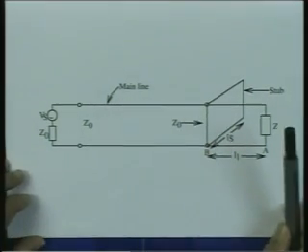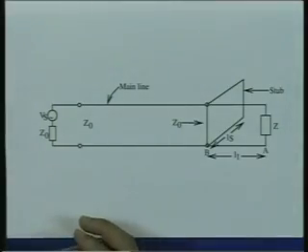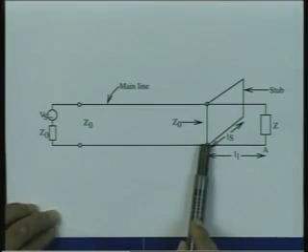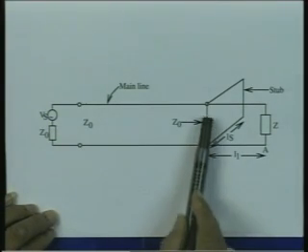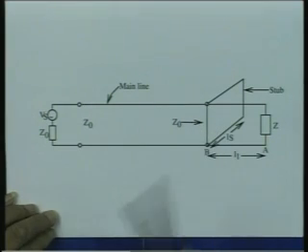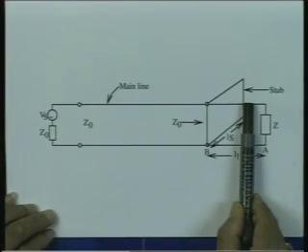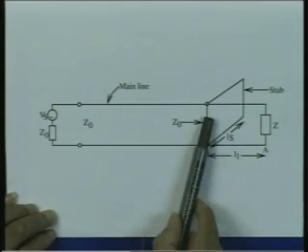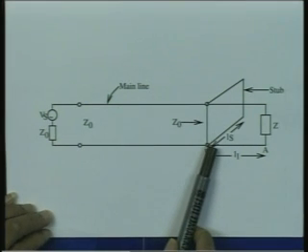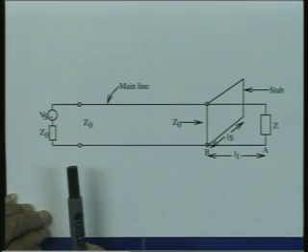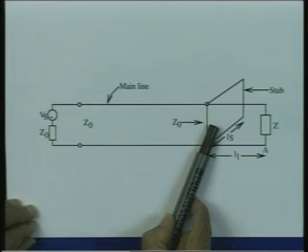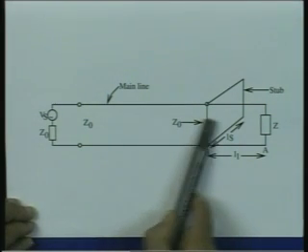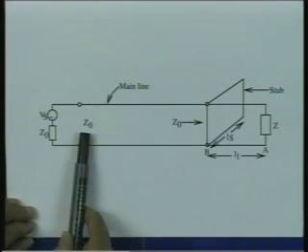Same thing we can say in different words from the impedance point of view. If I take this impedance and transform the impedance at this point, in general it will have a resistive and reactive part. The stub, which is short circuited, will always have a reactive part. If I make sure that in the parallel combination of the impedances which you see here, the reactive parts cancel, the impedance seen from here is purely resistive, and if that resistive part is equal to the characteristic impedance,